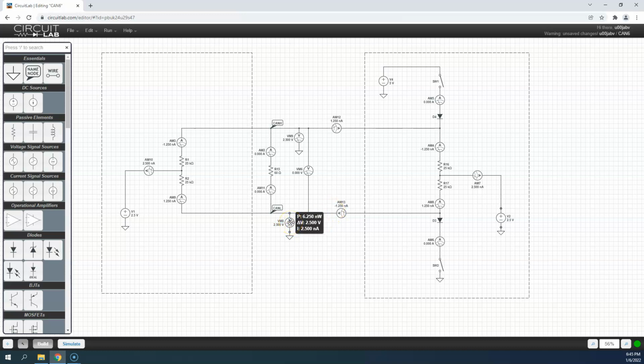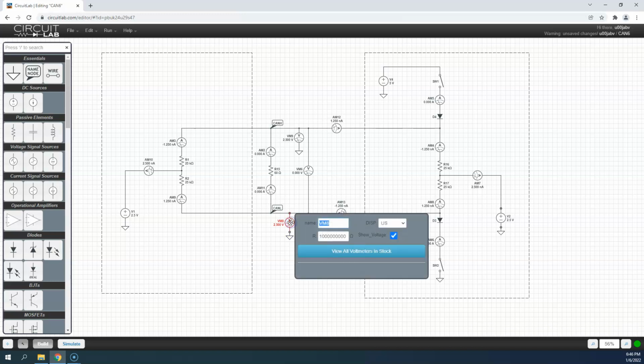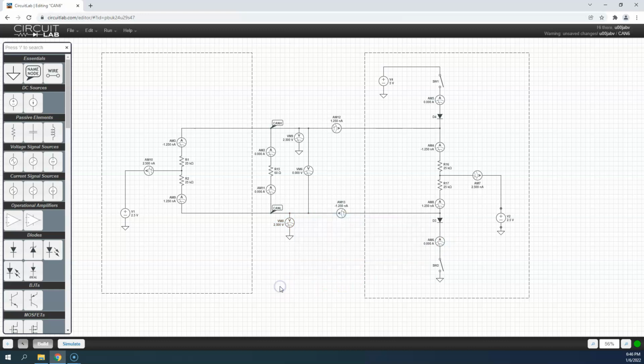As soon as I put my meter on the 9-pin connector and measure to ground, my meter models it as a whole bunch of resistance. I can't count the zeros. It looks like a gig of resistance. So that's a lot, if I counted the zeros right. I think I did. I think it's a gig. So that's a lot of resistance.